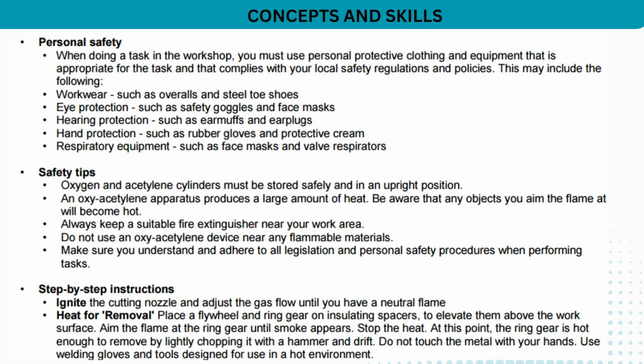Safety tips. Oxygen and acetylene cylinders must be stored safely and in an upright position. An oxyacetylene apparatus produces a large amount of heat. Be aware that any objects you aim the flame at will become hot. Always keep a suitable fire extinguisher near your work area. Do not use an oxyacetylene device near any flammable materials. Make sure you understand and adhere to all legislation and personal safety procedures when performing tasks.